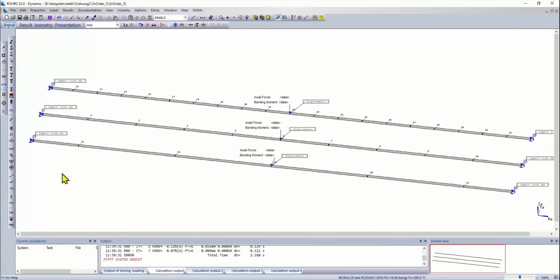So we can sum up that if you're using a pipe system configuration which is, let's say, reasonable with a support distance that is acceptable, then the pipe will be able to hold itself by the bending moments, and the secondary order effects are really negligible. It's only required for situations where you try to use the axial force to hold the pipe, and this is actually not a reasonable situation for most piping elements because they can get hot.